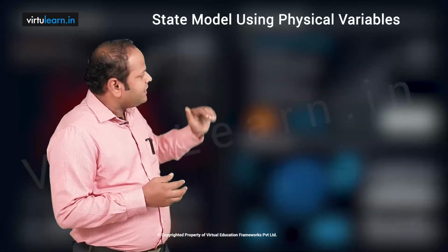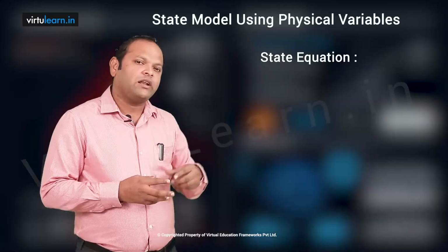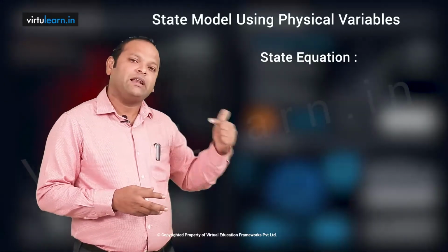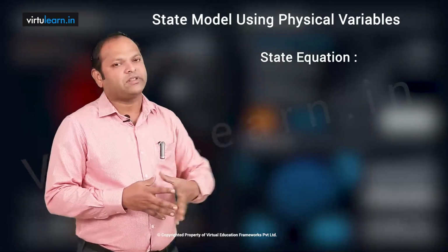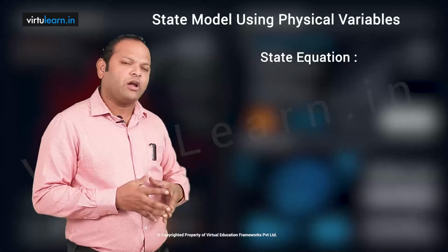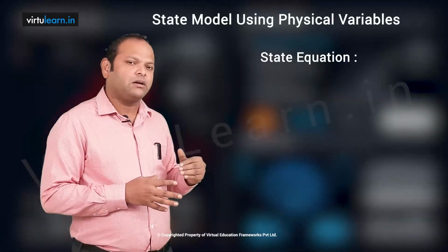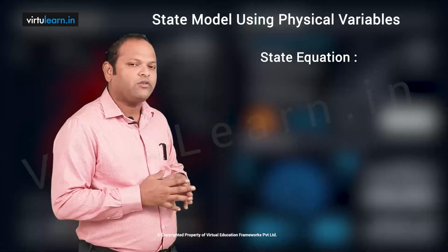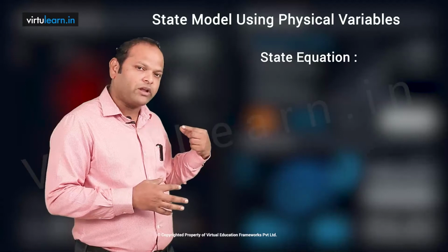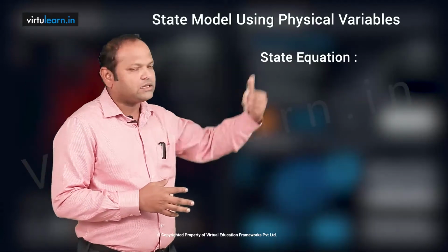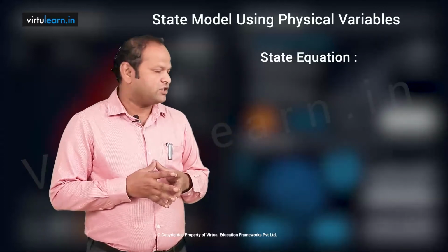When writing the equations, whenever you have an inductor, always write the voltage equation. Therefore I get L di/dt; I can write di/dt on the left-hand side and take everything else to the right-hand side. But whenever you have a capacitor, always write the current equation. Once the current equation is written, you get C dVc/dt. Therefore we write dVc/dt on the left-hand side, keep it, and move the other terms to the other side, so that I get the state equations.